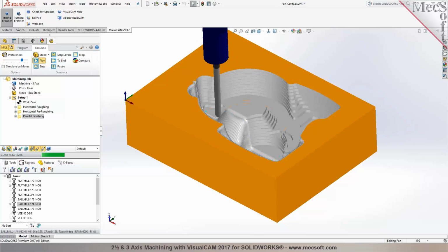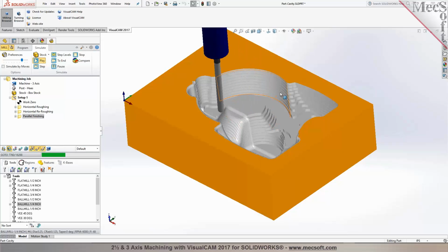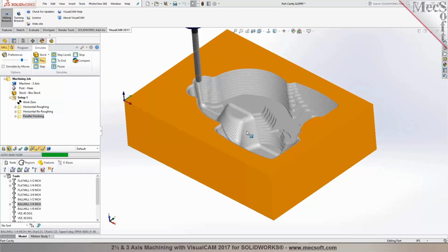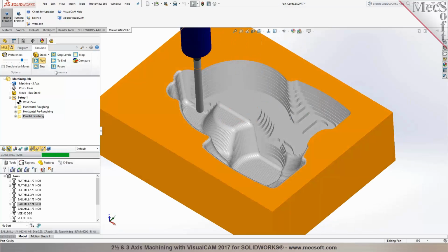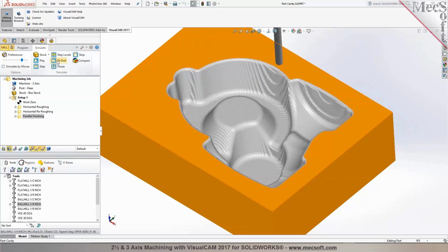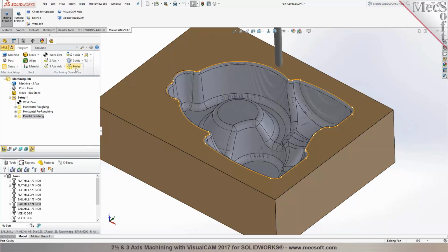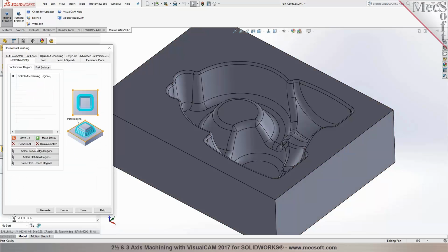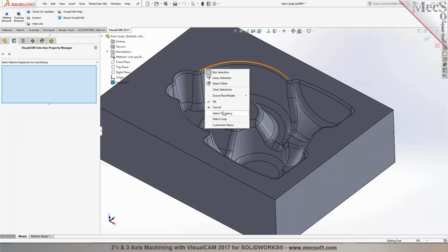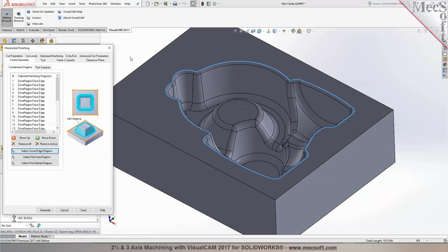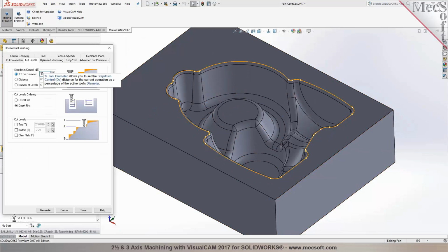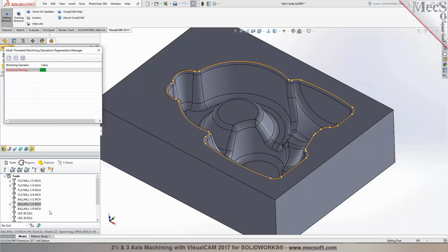So that's your finishing cut right there, pre-finishing cut. So you can always select pause and then simulate to end to run through the simulation. So there are different types of finishing operations we offer here. So this is parallel finishing. You could do finishing in levels known as D-level finishing. We also call it horizontal finishing. And I can again select the boundary in here to contain the toolpath, select the tool, specify the cutting conditions in here, and generate. So this will generate a finishing in levels operation.